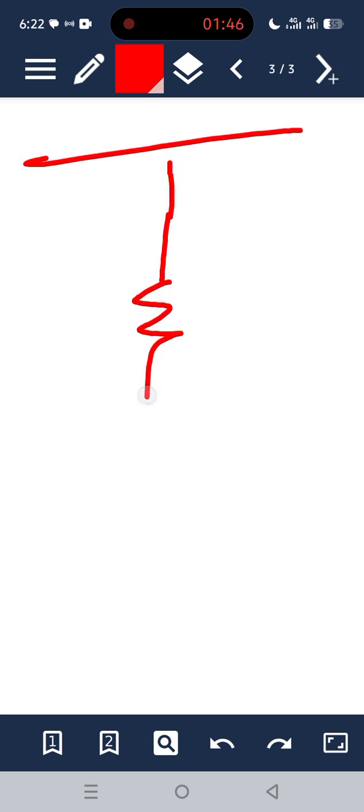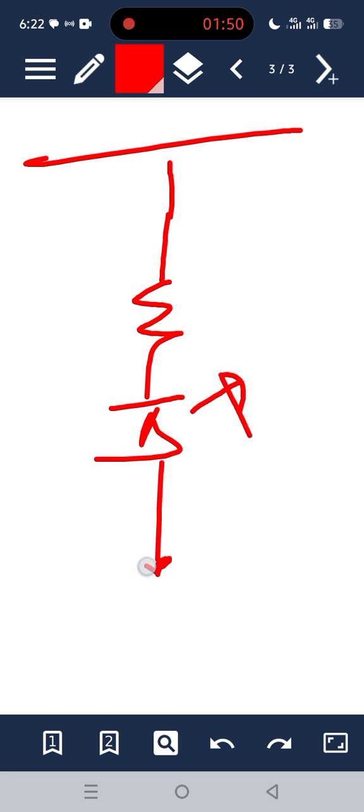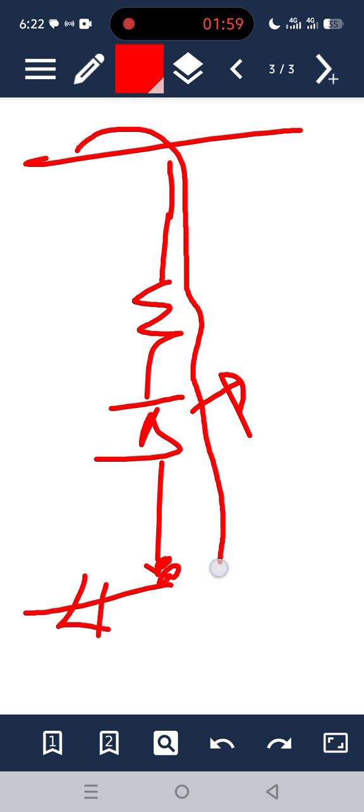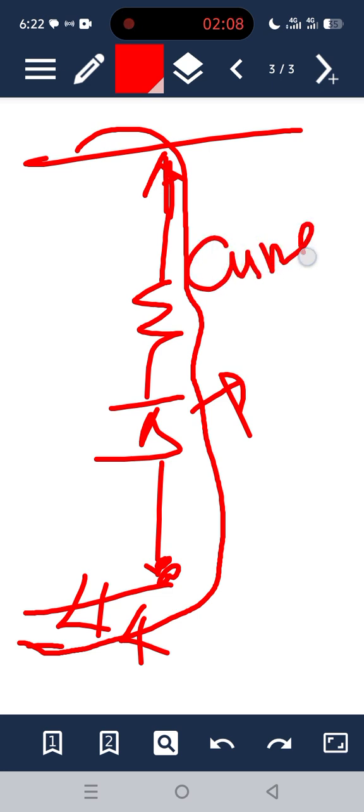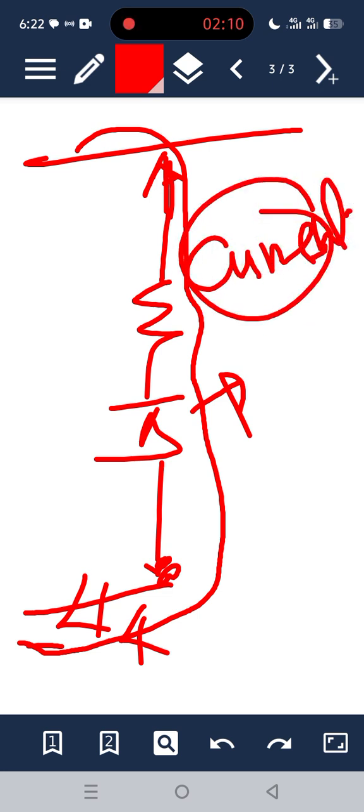So what happens is, this is the live wire. The phase tester is here, the resistor is there, then you have your LED here, then you touch here. Basically, when you touch this place, you create a return path. Electricity passes through this, through you, then through the ground, and returns. That is to say, whenever you touch that line over there, some current actually flows through you to ground to enable the LED to show. So what does that tell you?